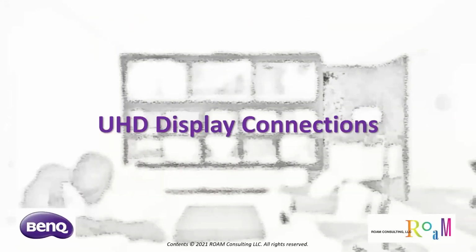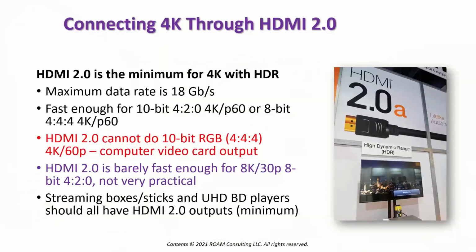How about connecting all this stuff? Well, the minimum interface that you need to show any kind of 4K or Ultra HD video with HDR is HDMI 2.0. This is a maximum data rate of 18 gigabits a second. It cannot go any faster. It can't pass any signal that requires a faster data rate.